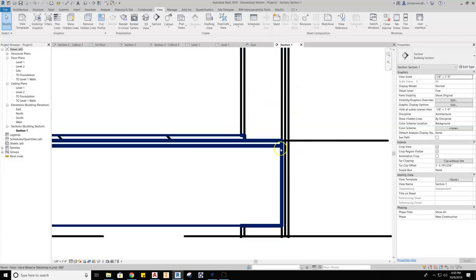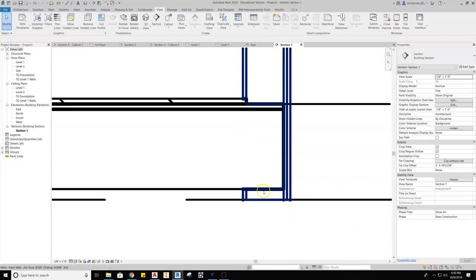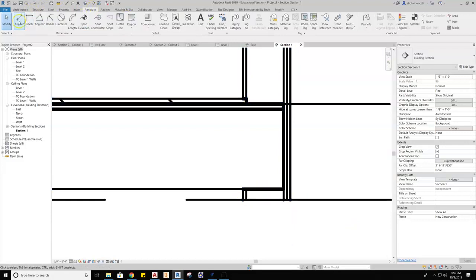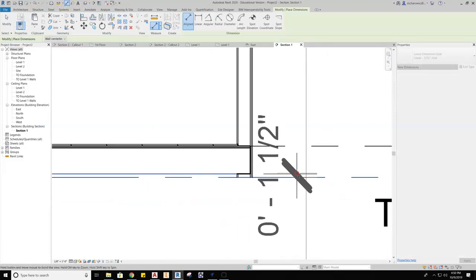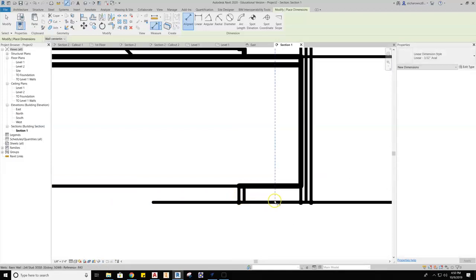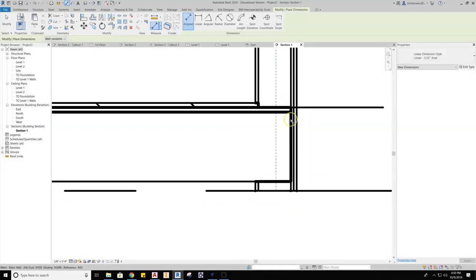The sheathing is running past the outside. The siding is running past the outside. What would happen in this location right here is where we would have our sill plate. And that sill plate would drop itself into position there, and the sill plate is 1.5 inches thick. That sill plate would reside directly underneath of the line of the wall and hold up the floor system.